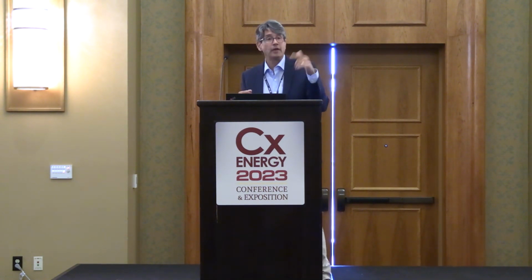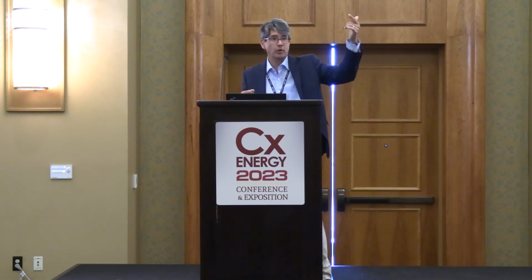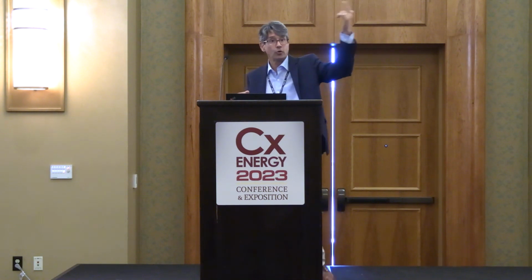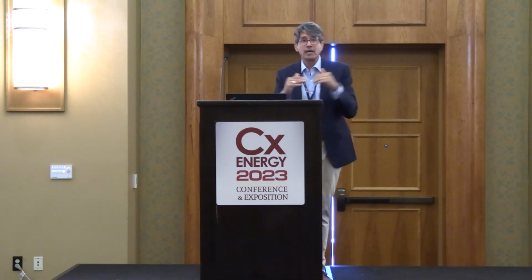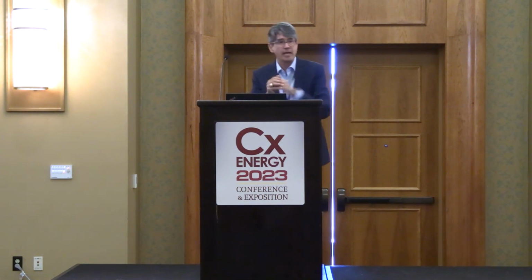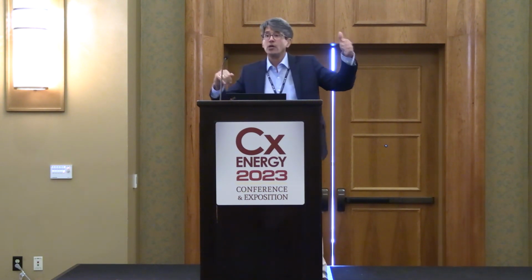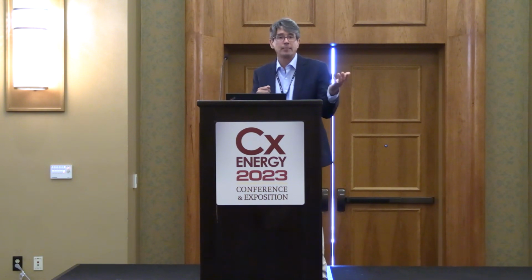A lot of times you'll have a VAV box up in those auditoriums, hidden by a cloud. How's the owner going to get to it later if the actuator fails? Hot water coils, strainers. A lot of those kinds of things in auditoriums, natatoriums, ductwork going over the pool. If we have that ductwork on the perimeter, a lot of times it's better. Things like that you've got to look at when you look at those drawings. We can save a lot of scenarios, and create a lot of opportunities to get airflow and water flow measurements, if we look at these things before it happens.